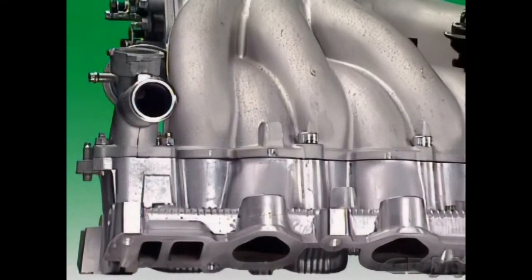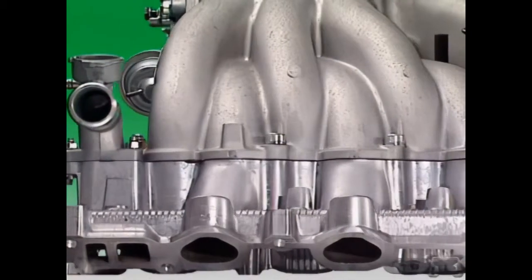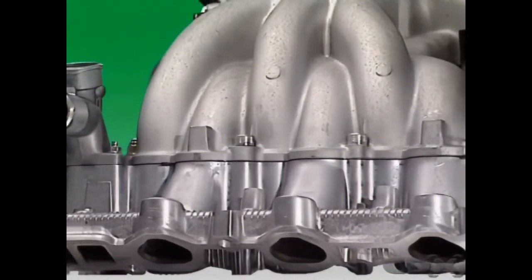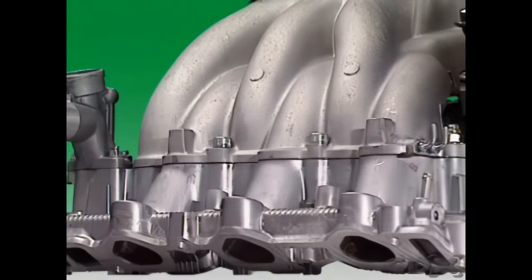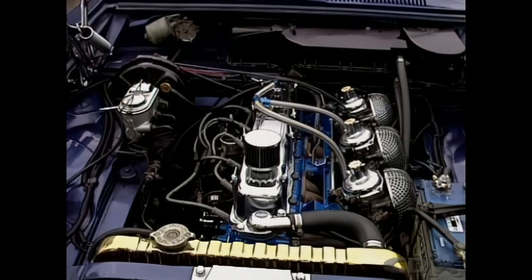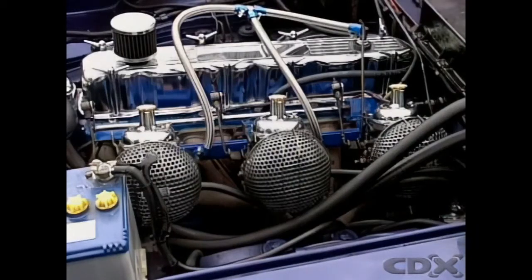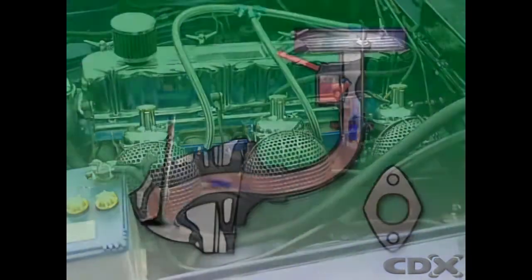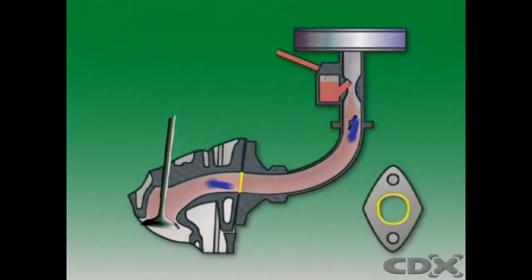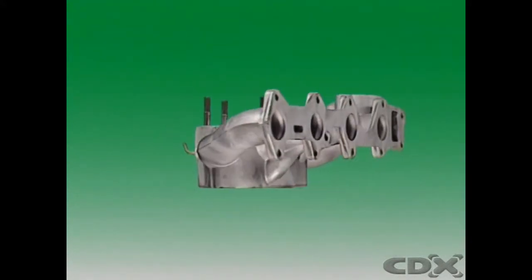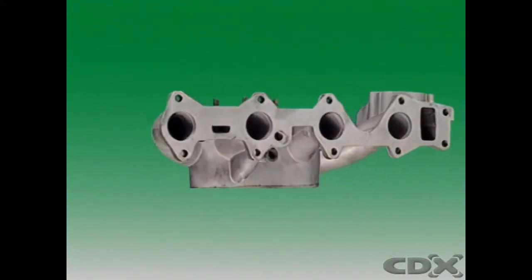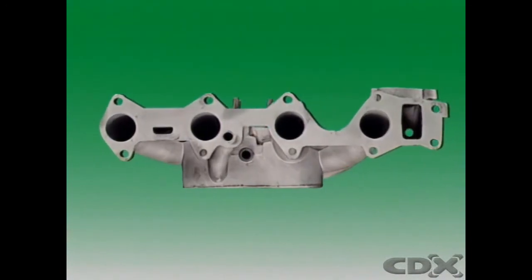The intake manifold is usually a metal casting with several tubular branches, though it can also be made of a special plastic. In carburetted engines, the intake manifold carries the air-fuel mixture into the engine. The cross-sectional area of each tube needs to be kept small to maintain the high air speeds that improve vaporization. At the same time, it cannot be too small, since that restricts the airflow to the engine at higher speeds.